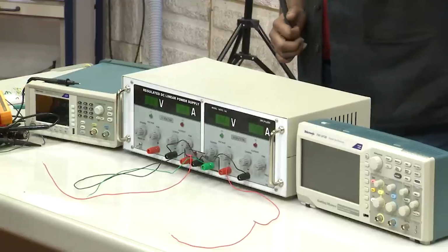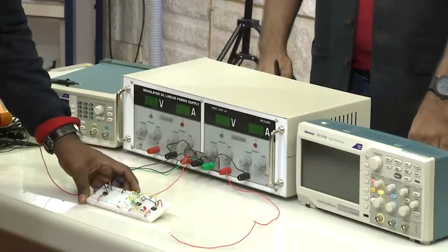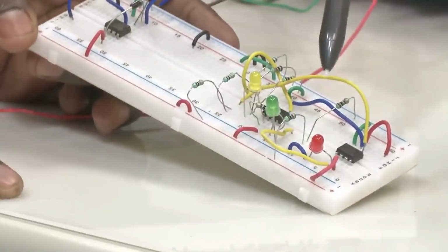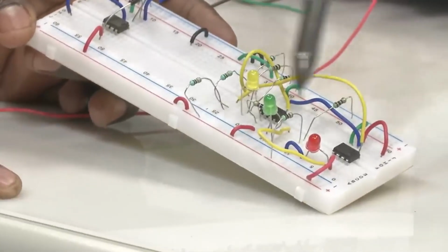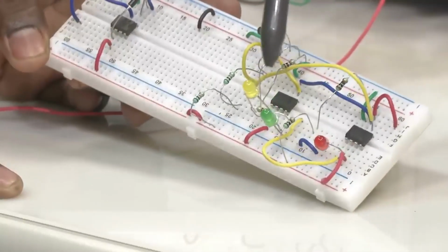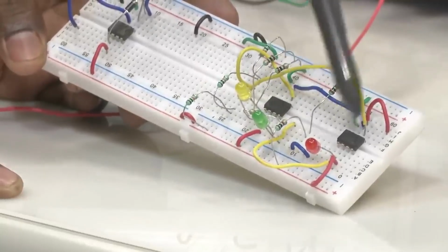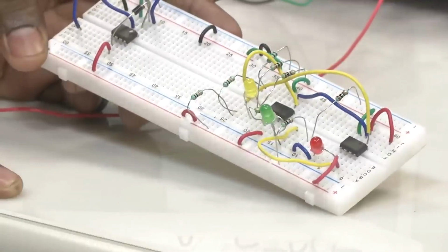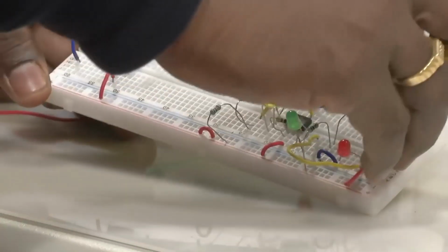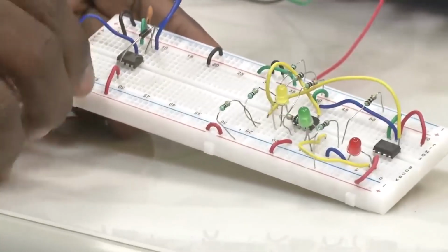So, now we have the breadboard. If you can focus on the breadboard, the circuit for the window detector is shown on it. Here also we have used red, yellow and green LEDs to indicate the output voltage. We can see here we have used resistors to form the reference voltages, and we have 2 op amps, 1 and 2, because we want to have 2 comparators. You can also use a dual op amp in this case, but we are using single op amps, because until now whatever experiments we have shown you use a single op amp. The single op amp is your μA 741.